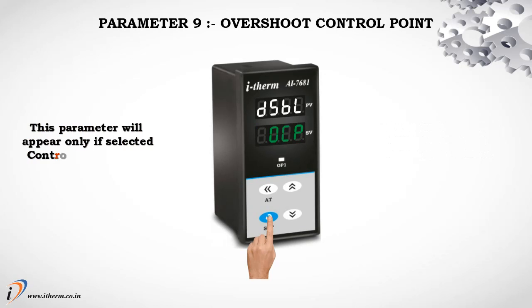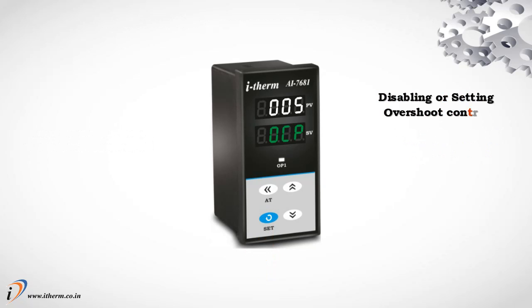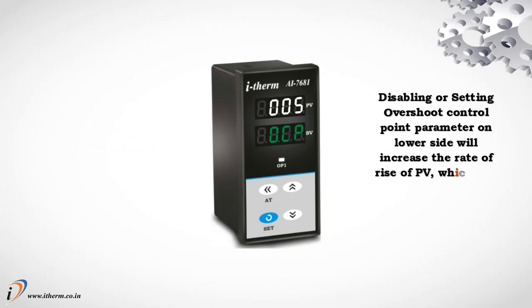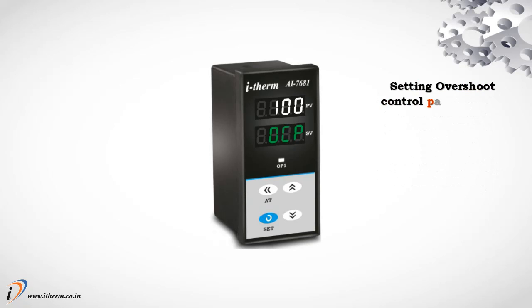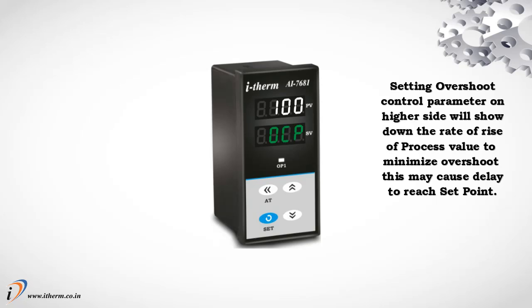Parameter 9, overshoot control point. This parameter will appear only if selected control action is PID. By default, value of overshoot control point is disable. Disabling or setting overshoot control point parameter on lower side will increase the rate of rise of process value, which may cause overshoot. Setting overshoot control parameter on higher side will slow down the rate of rise of process value to minimize overshoot. This may cause delay to reach set point.